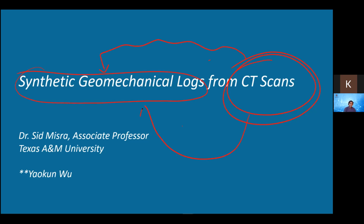So using CT scan, we wanted to generate synthetic geomechanical logs, which approximate the subsurface condition. So in the subsurface, there are some geomechanical properties. Let's say we cannot measure them. So the other alternative is you bring rock samples from the subsurface to the surface, you perform CT scans, and from the CT scans, we try to extract geomechanical logs. I'll tell you what I mean by geomechanical logs.